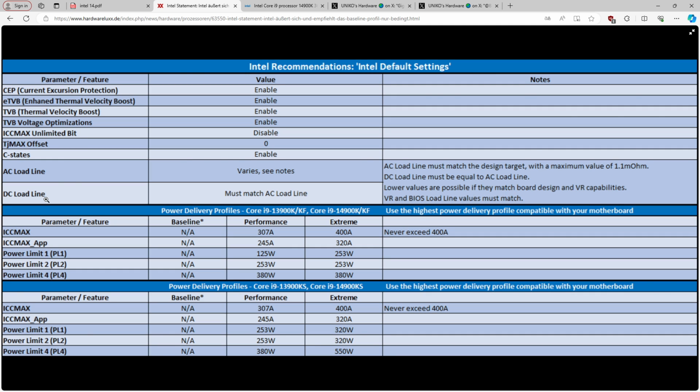So my suspicion for a while now has been that actually most of the degradation with these CPUs happens right at the start of a workload. So when the CPU starts working on something heavy and you get a huge current spike as it hasn't hit the thermal limit yet, right? Because as soon as it hits the thermal limit, it doesn't matter if your ICC Max is unlimited, it's going to throttle itself back. Though I guess depending on how fast the ICC, you could have some very quick current draw spikes even as the CPU is thermal throttling.